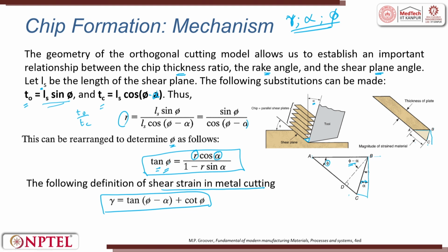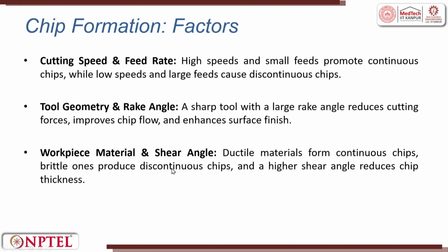Okay, can I measure phi? No, it is not possible practically. Alpha, can I measure? Yes, alpha is what you set as the rake angle on the tool. Can I measure R? Yes, R is nothing but the chip thickness Tc, which is the output of what you give in the process parameters.